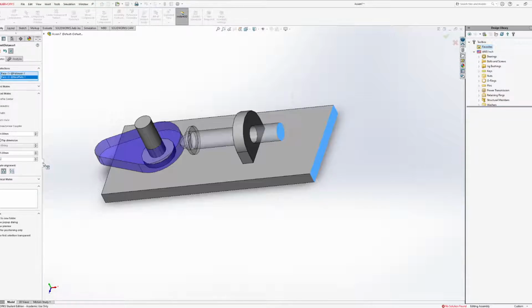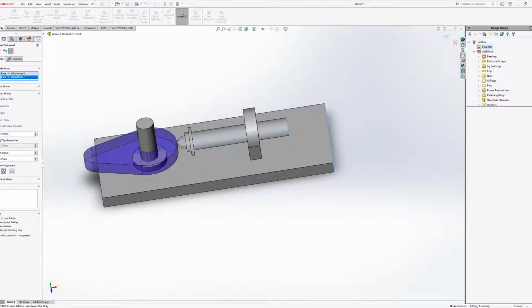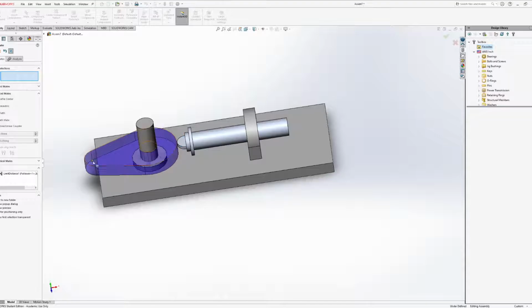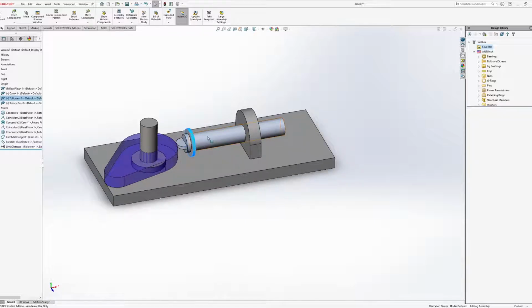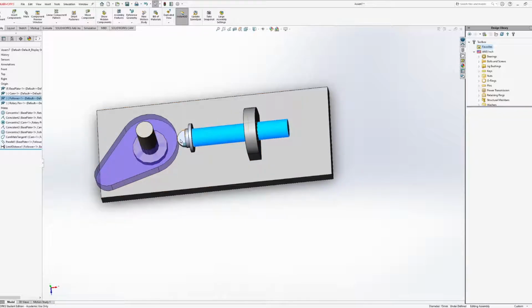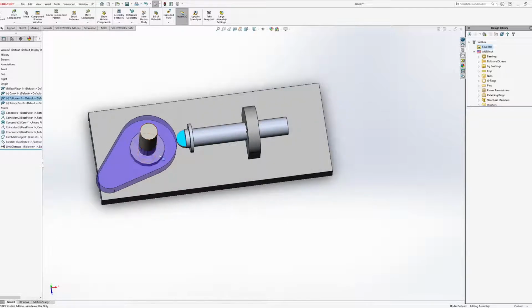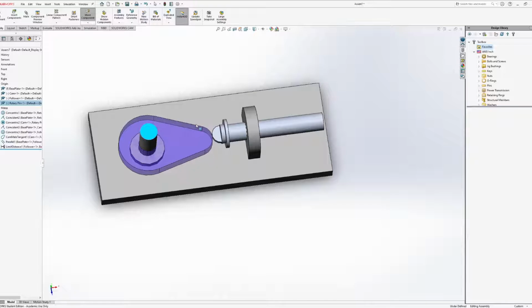I'm just going to put like 2.75, 2 3/4 of a millimeter. Then when I hit OK, there should be really no feasible way that I can just pull this over. You can see I'm kind of trying to move it, and it's really not doing a whole lot. You can see it's kind of moving a little bit, but it's not really moving when I'm trying to jerk it past where it should go. Things are still moderately underdefined, but by and large, that's really okay.